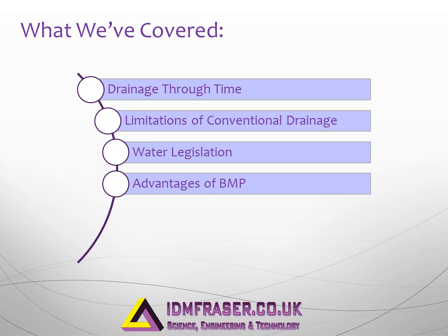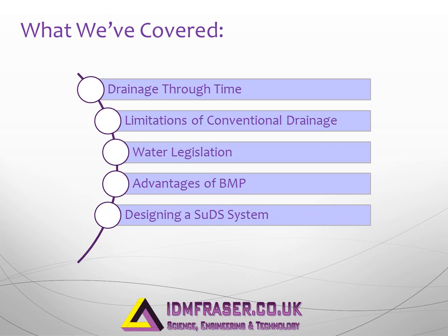Best Management Practice, or SuDS, can be used to transport surface water, provide a method of water treatment, provide attenuation and improve amenity. The SuDS triangle. To design a SuDS system, the catchment area, impermeable area, annual rainfall, ground conditions and nearest watercourse need to be obtained.